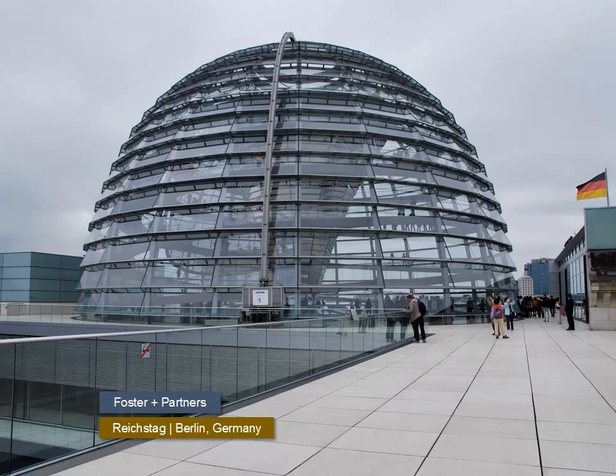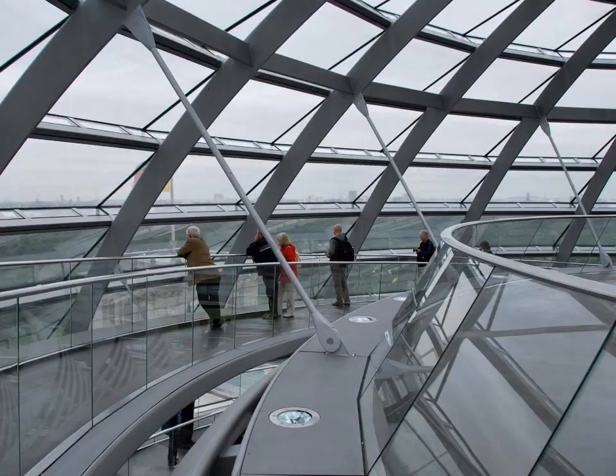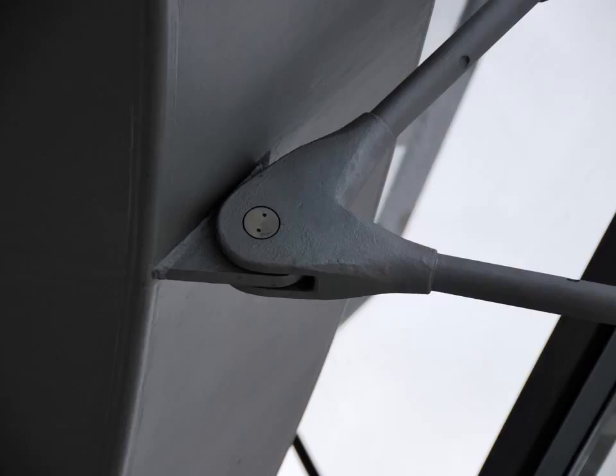Inside the curved glass dome of the Reichstag, a spiral ramp fabricated from custom sections of plate steel is hung from the ribs that form the dome. The spiral walkway inside the Reichstag dome uses a tension suspension system. The ends of the rods use clevis attachments. A custom clevis has been designed to neatly accept two incoming rods to simplify this connection.